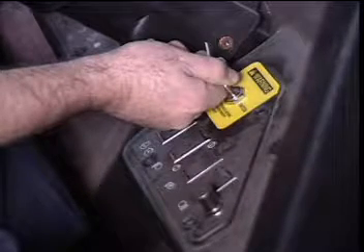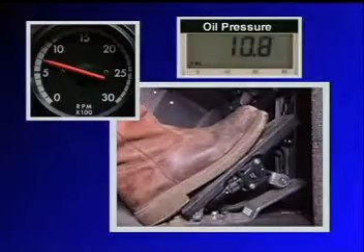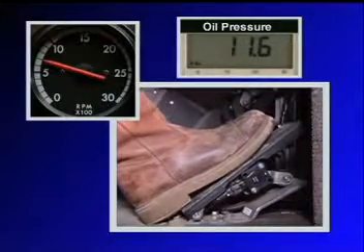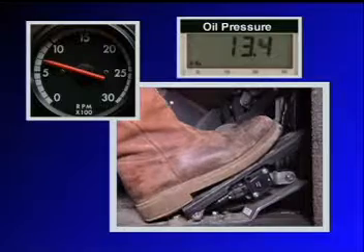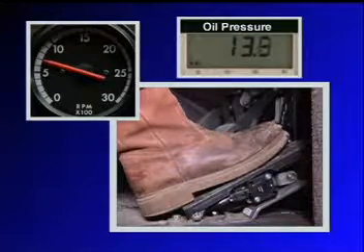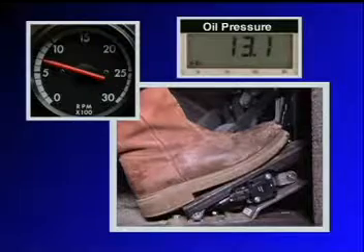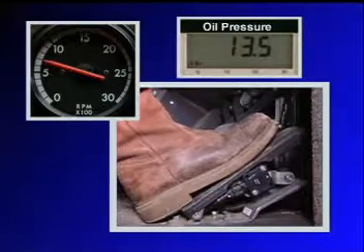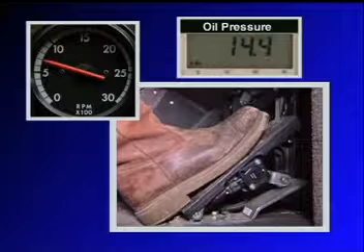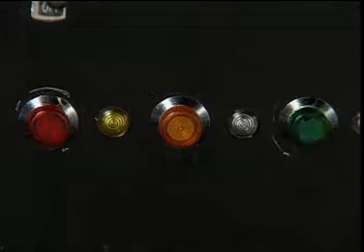It is beneficial to limit engine speed and torque after startup until sufficient oil pressure is available to supply oil to the engine components. Under certain operating conditions, not allowing the engine time to develop oil pressure before accelerating can damage key components, especially the turbocharger. The maintenance monitor feature flashes to indicate to the operator that the predetermined interval is approaching. When the maintenance monitor reaches its predetermined level, the ECM flashes the lamp after each key on until the maintenance monitor has been reset.